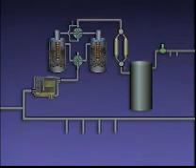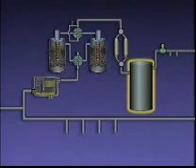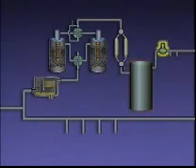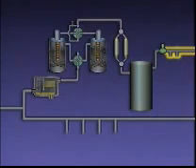Dry filtered air that is suitable for use in a control system is typically stored in a receiver until it is needed. Then it is sent to a pressure-reducing valve. The valve's function is to reduce the 120 psi air to 50 psi for use in pneumatic instruments and devices throughout the plant. The compressed air coming out of the pressure-reducing valve is distributed by an instrument air header. The instrument air header supplies 50 psi air for use in pneumatic control systems. This pressure can be further reduced by the devices that get compressed air from this header.